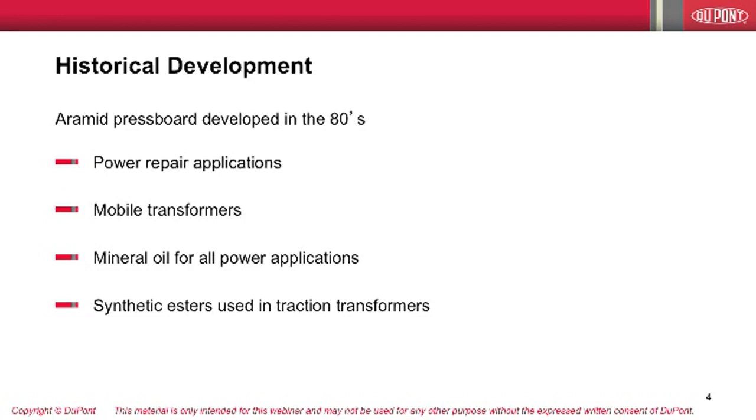High power density mobile transformers also became available to meet the increasing needs for temporary replacement power. All of these applications took advantage of windings operating at high temperatures, but still used mineral oil operating at normal temperatures. The hybrid transformer was born.